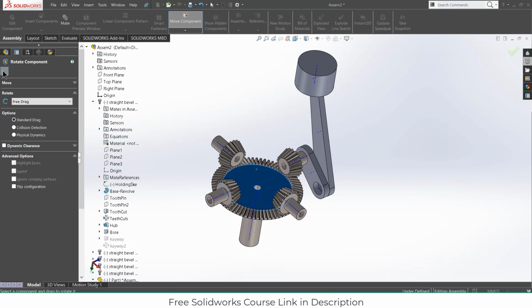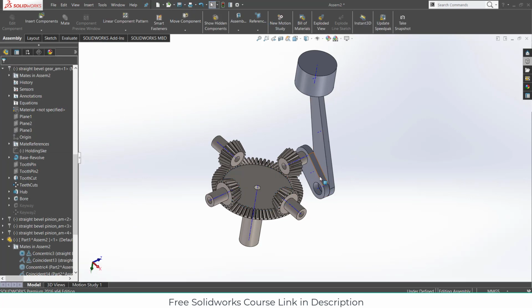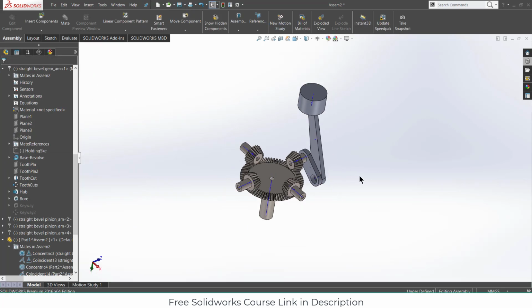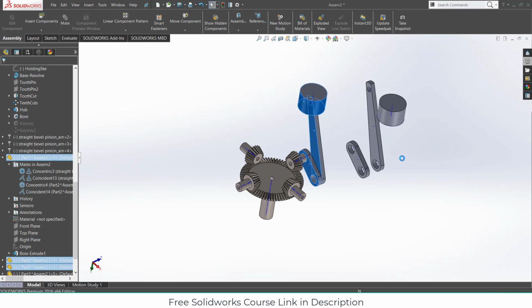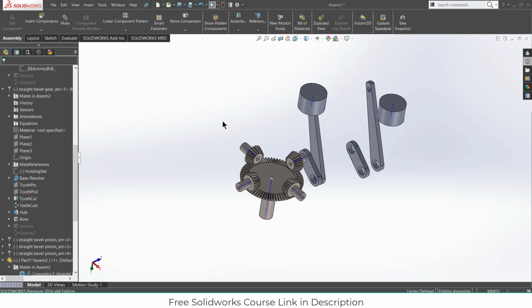So what I'm going to do is, I will import all these parts. Not going to import this, drag and make again the mating. So let's see how do I do it. By pressing Control, right click on your mouse, drag it. So this is one. I need three more. So what I can do is Control and drag it.